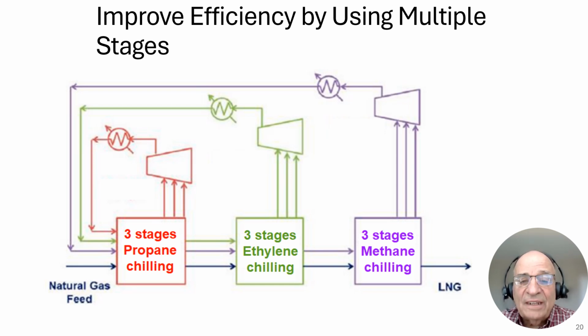And these are fed into the ethylene compressor, and that starts all over again. But take a look at what's happening in the ethylene chiller. It's chilling down both methane and LNG, and that chilling is being done by the ethylene that's coming in this top stream, going to the JT valves.